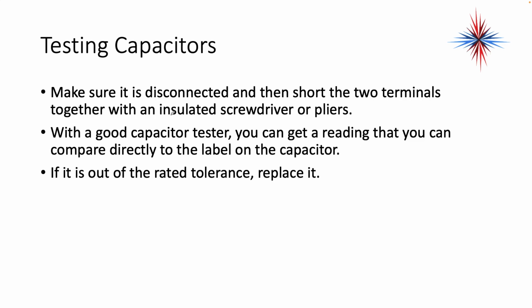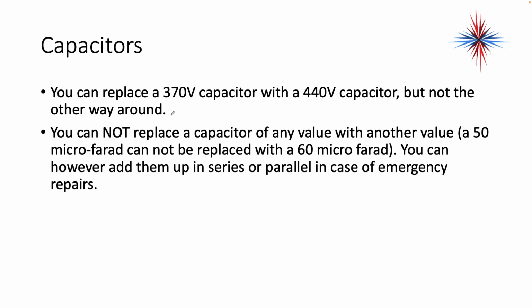Okay, to make sure it's disconnected, then short the two terminals together with an insulated screwdriver, pliers, or preferably a bleed resistor. With a good capacitor checker, you can get a reading that you can compare directly to the label on the capacitor. If it's out of the rated tolerance, replace the capacitor. Don't mess around with capacitors that are out of tolerance. It's not good, and it will eventually lead to burning out motor windings.